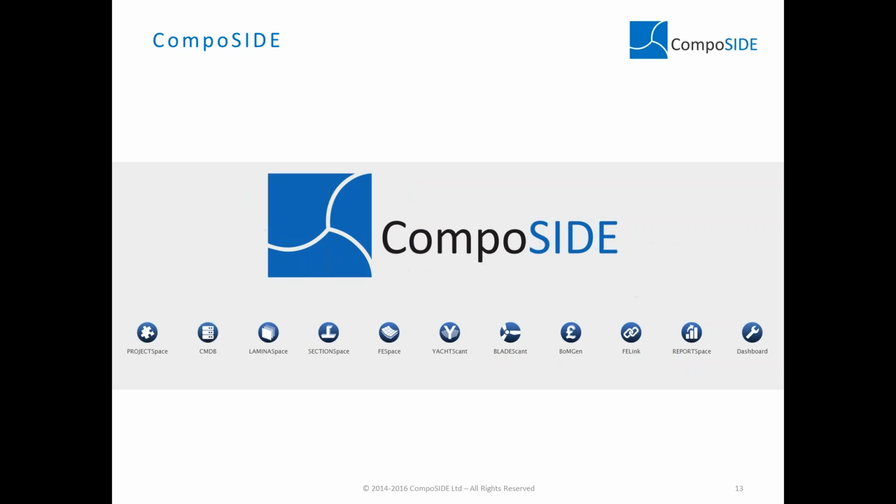FE space is the module dedicated to 3D modeling and FEA. As John mentioned, you can import files or create your own directly within the module, and it automatically generates a mesh for your linear and buckling calculations. The same mesh is then used to evaluate material quantities, weights and surfaces in the bill of materials. And finally, BOMGen is the automatic bill of materials generation module. It automatically calculates everything related to weight, surfaces and all the costs for the structures that are defined within your same project.